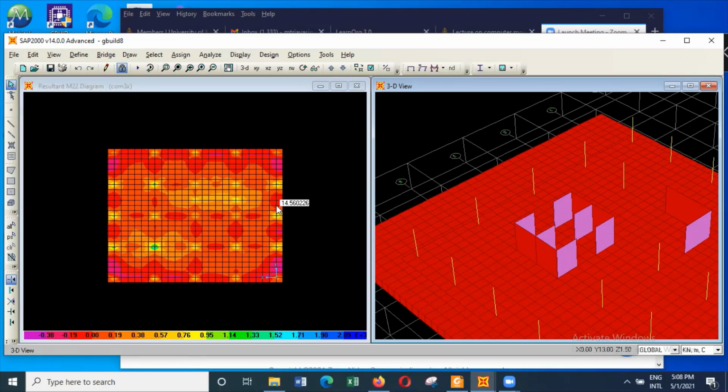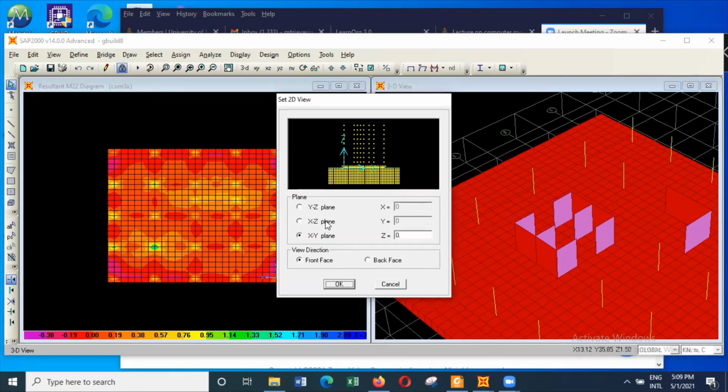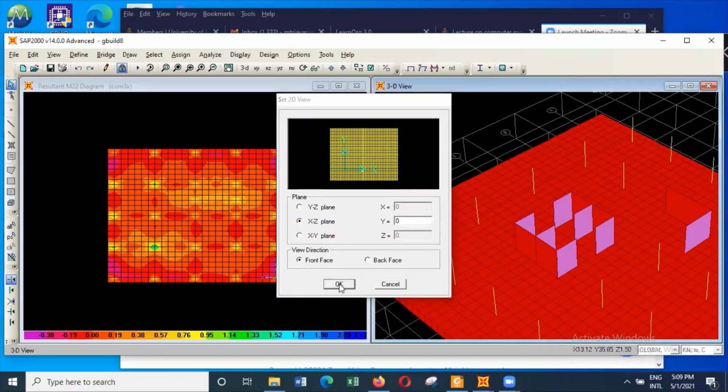Bottom slab moments are okay. And then when you look at the distribution of the soil pressure, that also goes into concentrated areas, because the deformation of these ribs will be lesser than the deformation of the slab. So the soil pressure under the raft will not be perfectly uniform. But overall, you can see it actually gives us a clear idea about the variation that we can expect.